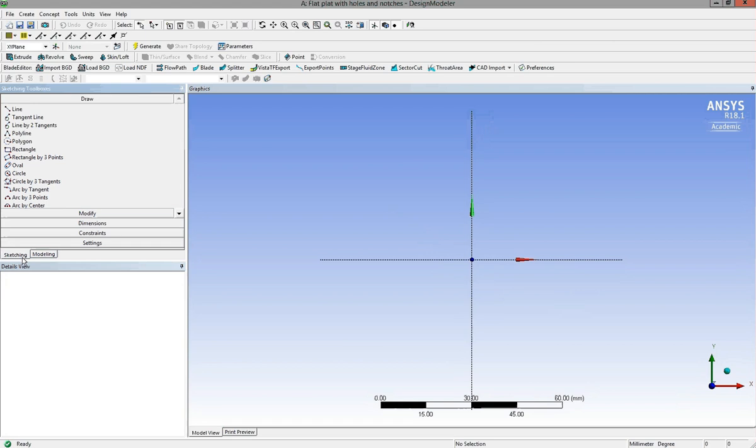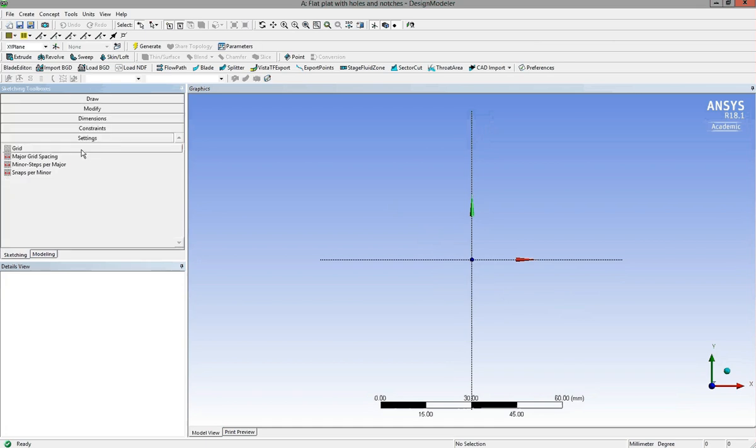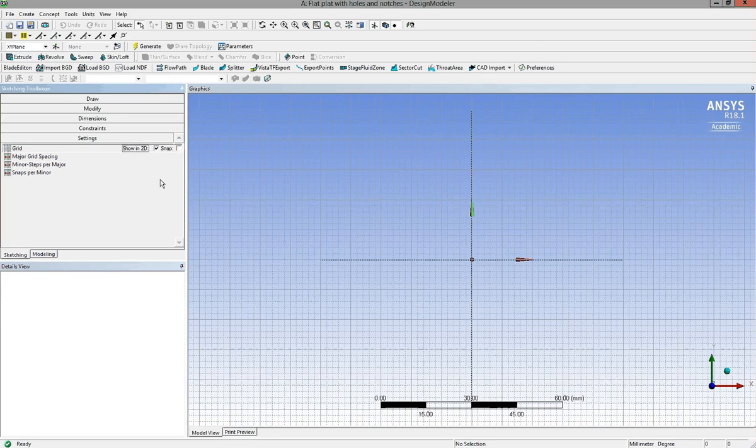Now it can be convenient to switch on a grid and make sure that it snaps to the grid. You don't have to do it. I'll use both the grid and dimension lines and they're alternative ways perhaps of doing things. But I'm going to show the grid first of all. It switches on. The major grid spacing 10 millimeters. That seems reasonable enough, I think, at the moment. Yeah. So I'm going to have one minor step. So I'll change that to 1.